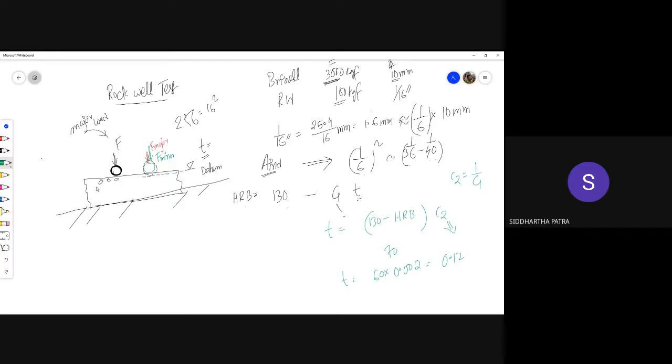That level is now the level beyond which you make any measurement. The next thing you do is apply the major load, and the indenter proceeds further into the material, creating both elastic and plastic deformation of the specimen. Then you remove the major load while the minor load is still there.